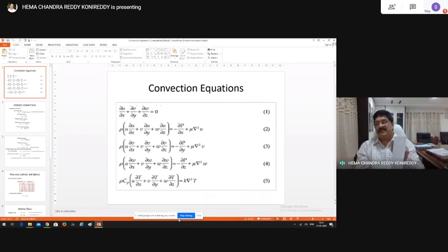So if you find a velocity profile like this, velocity is zero at the surface, slowly it increases, reaches a maximum, and thereafter it falls, and a boundary layer is formed. If it is a colder surface, and hot air comes in contact with it, the air becomes cooler because it loses heat, and therefore becomes heavier. It wants to move down. Heavier particles always move down in the medium. So these heavier molecules lose their heat, their density increases, and therefore they move down. So a boundary layer is formed from top to bottom.